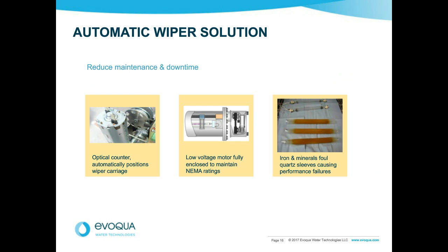Wiping is critical. The wiper is a seminal and critical part of a UV system. The water will foul. If you're using a pasta flume or if you're using water to move carrots or peas or potatoes, if you're using brines, part of the preparation of cured meats involves lots of very cold, deeply chilled brines, these will all deposit foulant on the surface of the quartz.